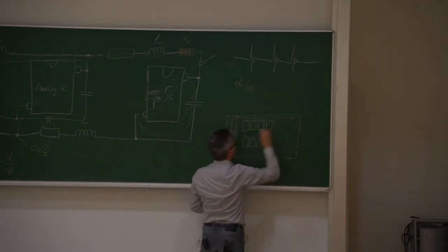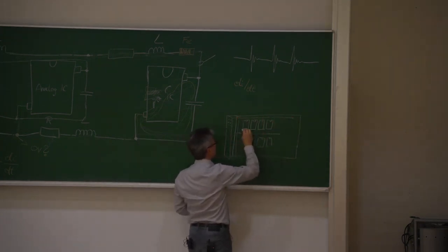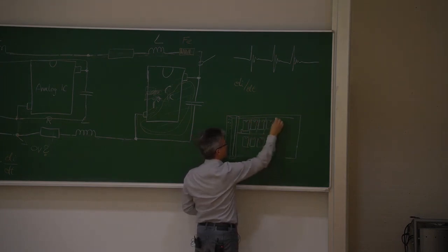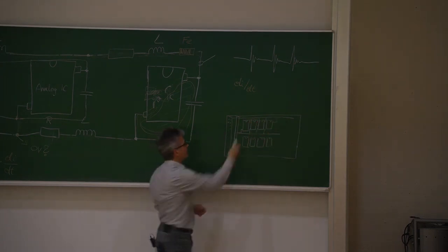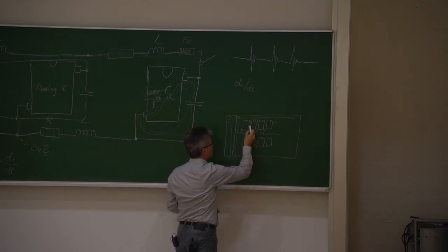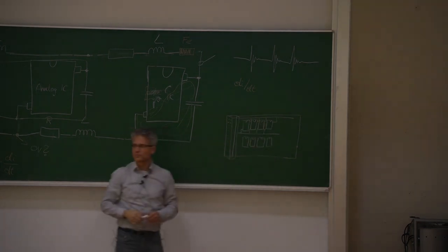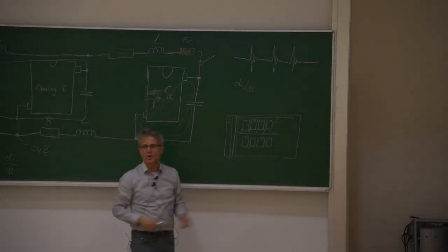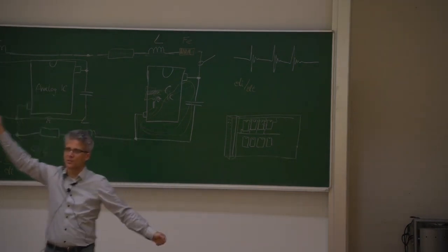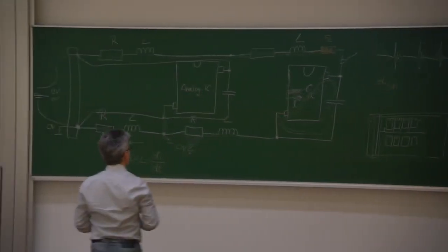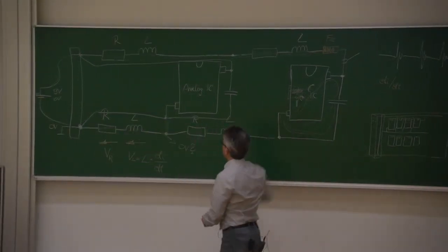And then it was very simple to route VDD and ground, because you can route a big ground trace here and a big VDD trace over there. And then in between you can connect, somewhere below the ICs, all the digital inputs and outputs. And this was the only reason why they placed the VDD pin here and the ground pin there. Definitely not for EMC reasons. Okay, so a very good solution would be to place VDD and ground next to each other.